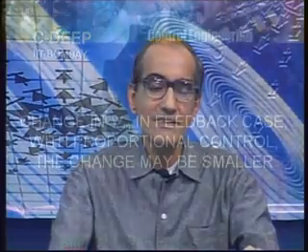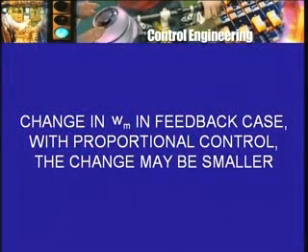The very preliminary crude open loop situation, in which we just applied 230 volts to the armature and did nothing about it, let the load torque vary, the motor speed will vary by a small amount, because after all the DC shunt motor is a good one for constant speed operation, and if that change of speed was tolerable, well and good. So there is nothing being manipulated, nothing being adjusted, no actuation of any kind. 230 volts fixed applied with load torque changes, the speed would change.